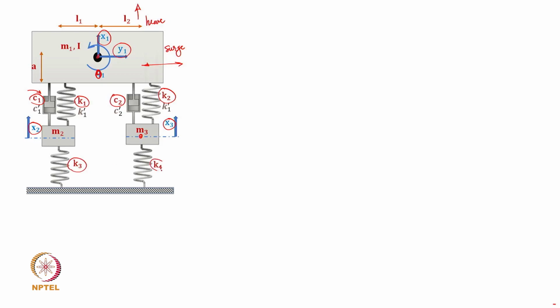K3 and K4 now quantify the tire stiffness, because the wheel mass is separated from the ground through the compliance of the tire. Based on the tire characteristics and the air pressure, it will have its own stiffness. In general, this stiffness is nonlinear, but for the sake of initial analysis, it will be considered a constant stiffness K4 and K3.